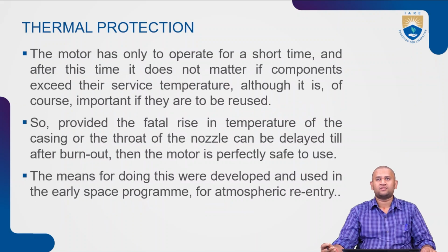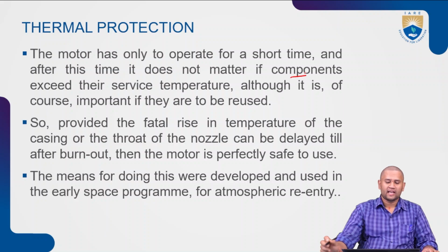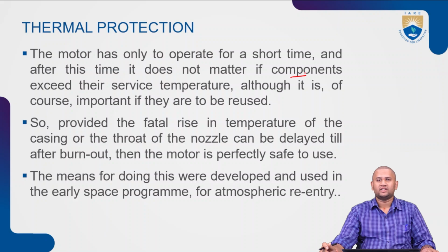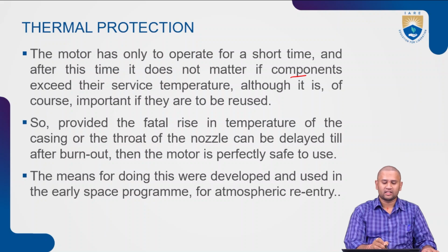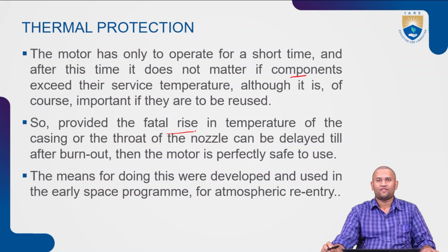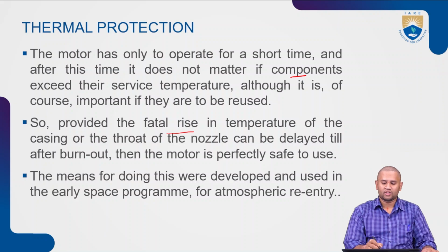The motor has only to operate for a shorter time, and after this time it doesn't matter if the components exceed their service temperature, although it is of course important that they are to be reused. So provided the fatal rise in temperature of the casing or the throat of the nozzle can be delayed till after burnout, then the motor is perfectly safe to use.